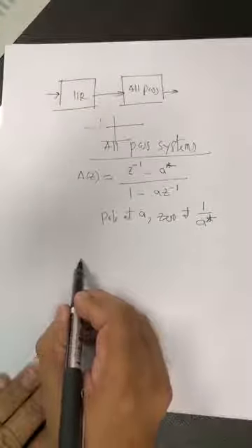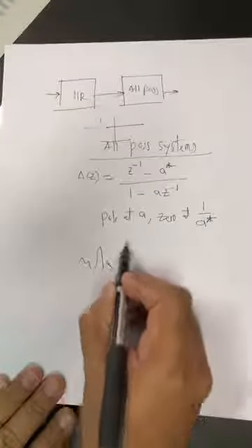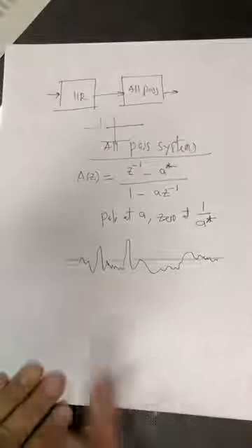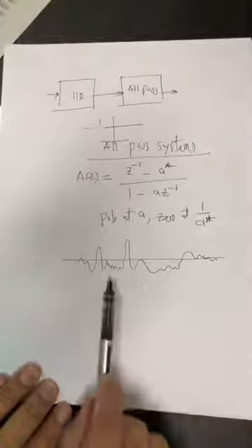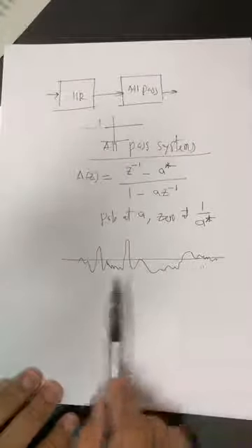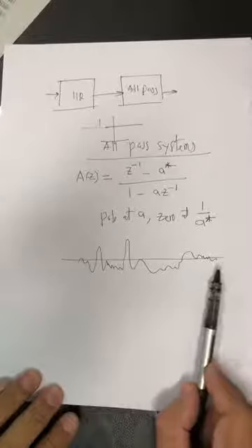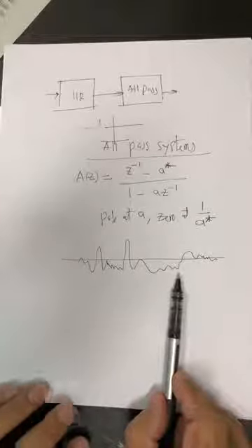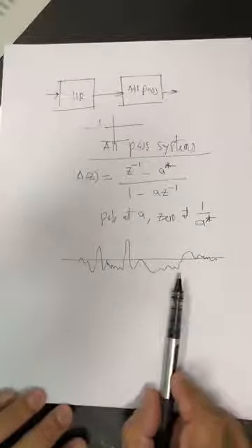Your signal usually has different frequency contents, and once we are filtering, we don't want the relative positions of these frequencies to change, because if they change, it will change the shape of the signal, which usually we don't like in many applications.